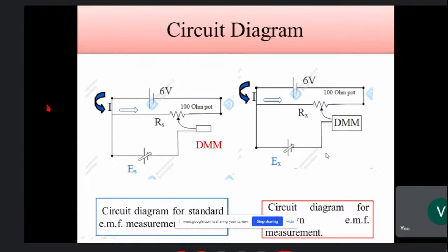And not only that, sensitivity matters from the point of view of getting a deflection at the galvanometer when it is away from the null point. That is more important. Nowadays, in our experience, we always use digital media, because galvanometers are not easy to manage at home. A digital multimeter can show zero current in the microampere range, highly sensitive. That's the purpose. It gives the null condition, and that can be checked by digital multimeters.